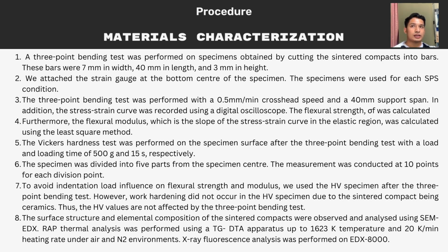In addition, the stress strain curve was recorded using a digital oscilloscope, and the flexural strength was calculated using the typical formula. Furthermore, the flexural modulus, which is the slope of the stress strain curve in the elastic region, was calculated using the least square method.